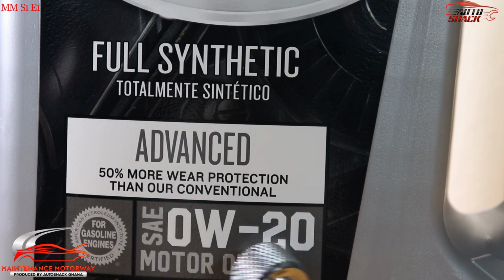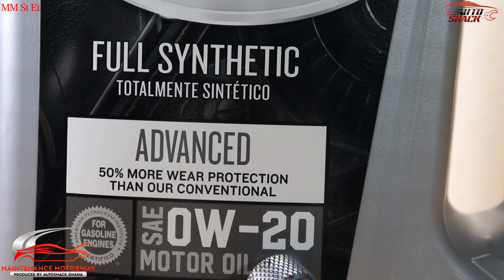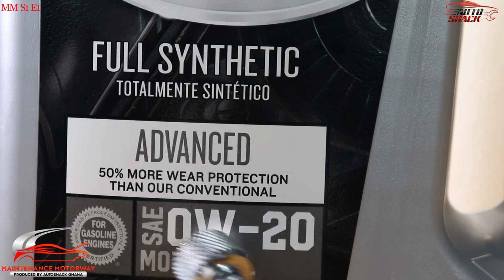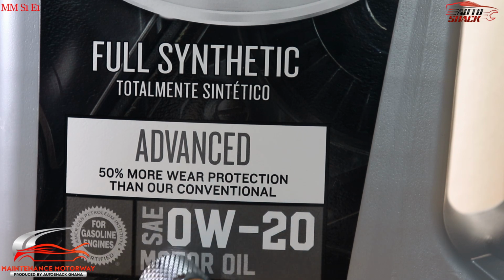And this 20 means it needs to not be too thin at engine operating temperature, which is about 212. If it's too thin, it can't protect the engine. And if it's too thick and doesn't flow quickly, it can't protect the engine either. So it needs to have these two viscosities. That's why it's multi-viscosity.